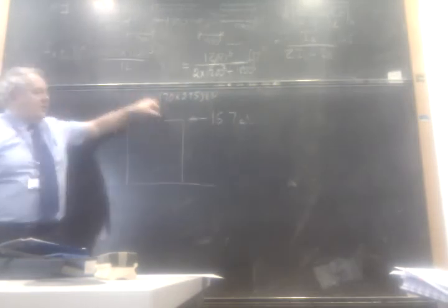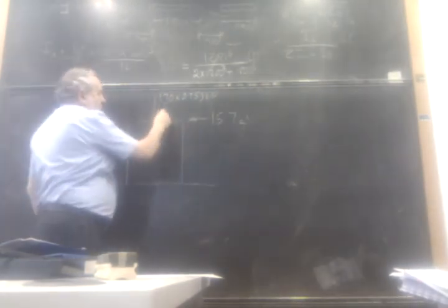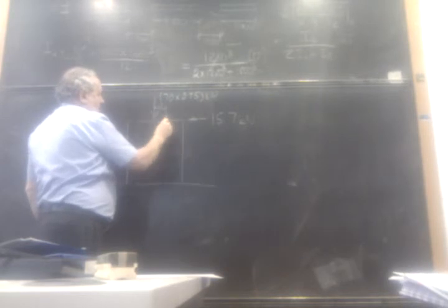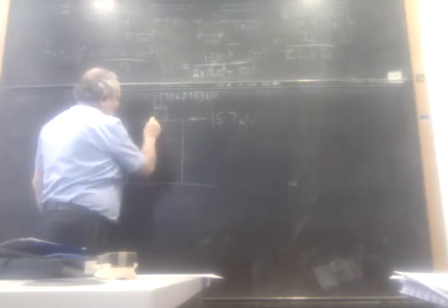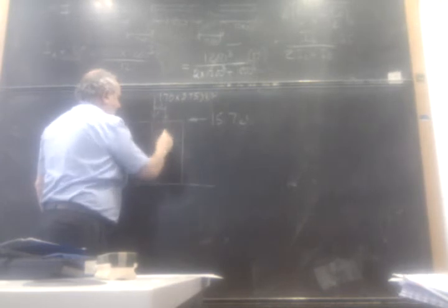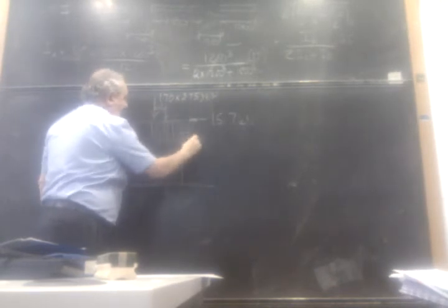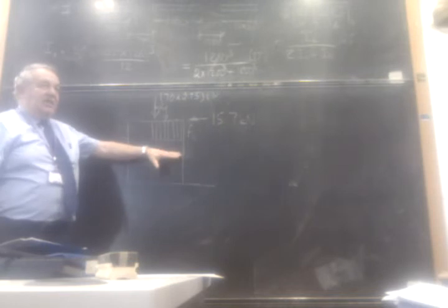And there we are. So you know the vertical load, you know the horizontal load. You can work out the eccentricity E, eccentricity at that end, and the eccentricity at the other end. FK, as I just did a minute ago. Should be that bit. In the problem, it gives you these three formulae there, and it's then just a question of checking the middle fifth of the wall. Yeah, but that scares me. That'll just mess me up.